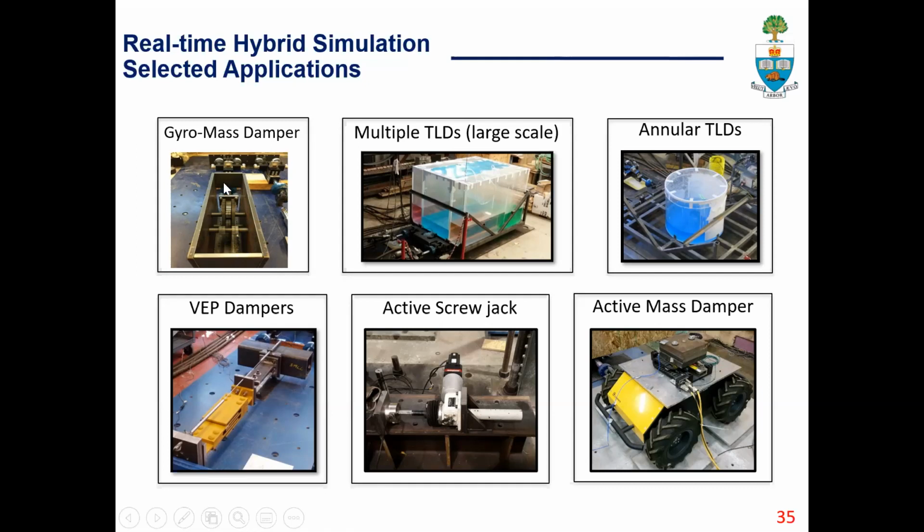And in order to study the effectiveness of this new device, we performed real-time hybrid simulations for single degree of freedom analytical substructures, which represented the first mode of the structure. In the next two examples, we are again using tuned liquid dampers.